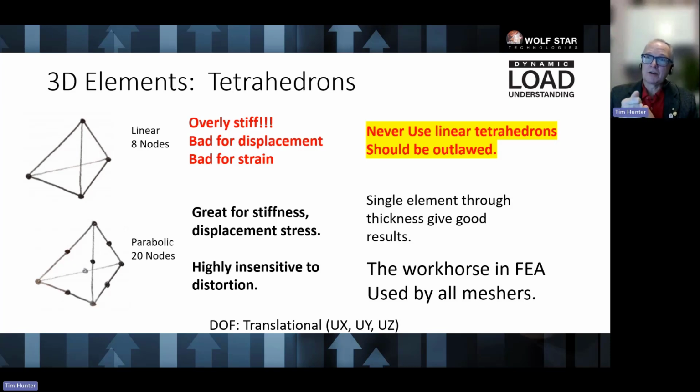I have gotten so many meshes from customers that are linear tetrahedrons that I just have a heart attack when I get them. Okay, so be very, very careful with that.